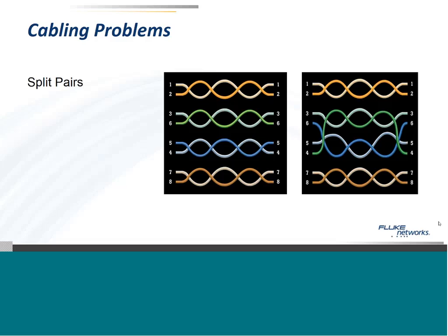If you have cable in bundles, you not only get crosstalk between the pairs in the jacket, but between adjacent pairs. And there are ways to test for that, and if you have a contractor that knows how to do that, that's the way to check for that. It's a fairly easy test, especially since you only have to test the cables that you want to use for your access points. But I'd go to the NBASE-T Alliance website and find their white paper on cabling, and it explains exactly how to do that.